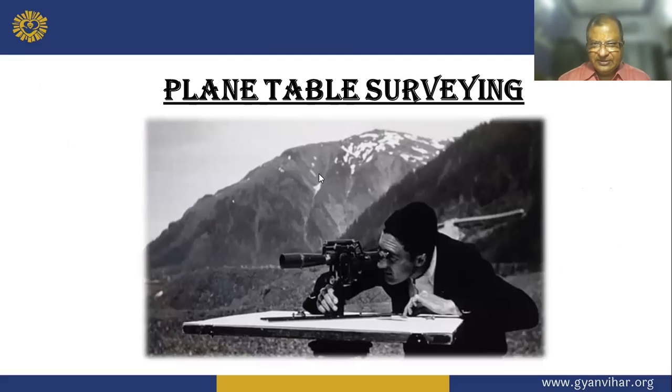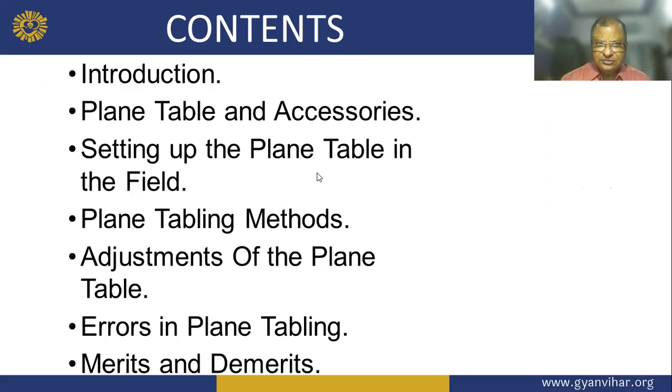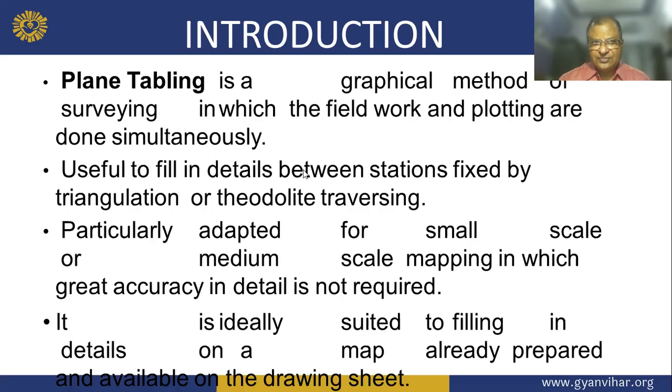My dear boys, this is the plane table photograph, and the contents of this introduction are: plane table and accessories, setting up the plane table in the field, plane table methods, adjustment of the plane table, errors of the plane table, and merits and demerits. The plane table is a graphical method of surveying in which the field work and plotting are done simultaneously.